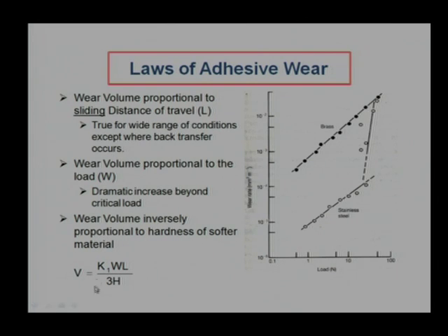This wear constant can be manipulated. We can do a number of experiments. We assume this is a curve fit equation, find W, measure L and measure H. Based on that, whatever the wear volume comes out to be, we can appropriately find K1. If we do 30 or 40 experiments, the statistical variation of K1 can be estimated easily with some standard deviation.